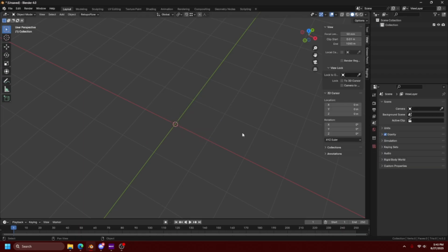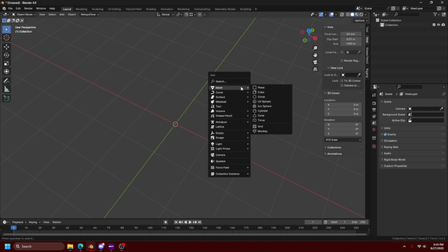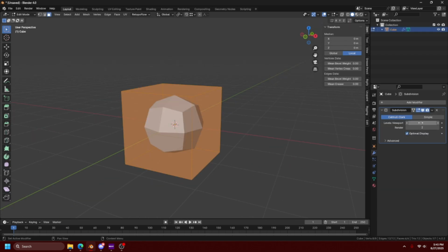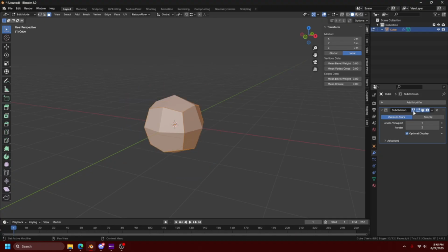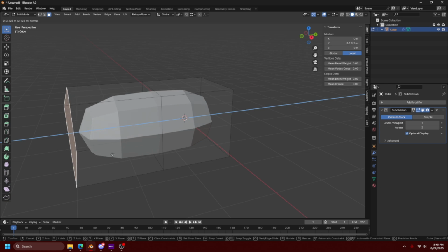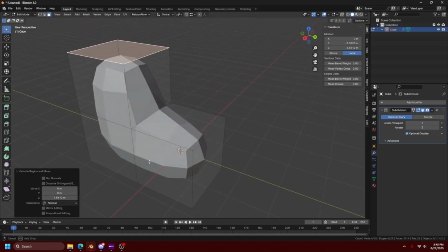The last one I want to talk about is the subdivision surface modifier. Now, a lot of people use the subdivision surface modifier and they use it to model. I do not like this. This thing, on cage, it's nice, right? Like you look at it, and it's like, oh, look, I can transform the mesh and everything changes along with it. I personally think, especially if you're a beginner, turn this off, because it's more understanding of 3D form if you do it with the cage off, because you can see the outside, what you're doing and what it's resulting in on the inside. So I think it's a lot better for learning if you do it with the cage off.